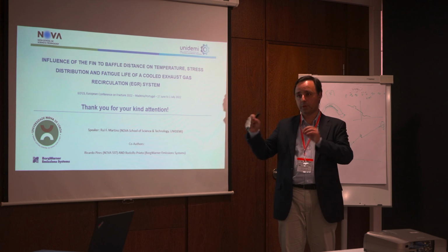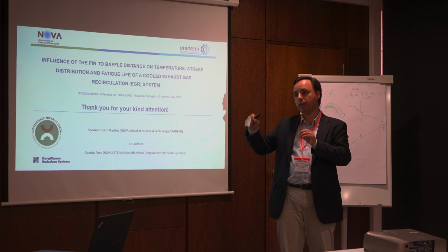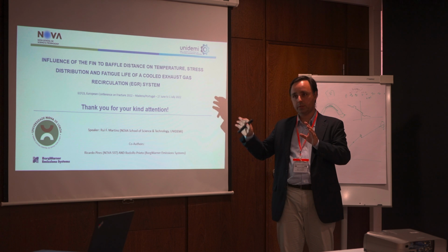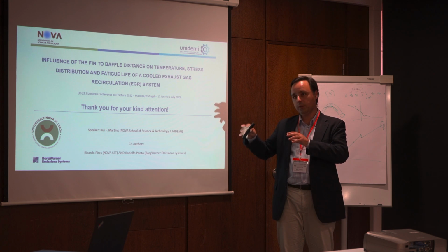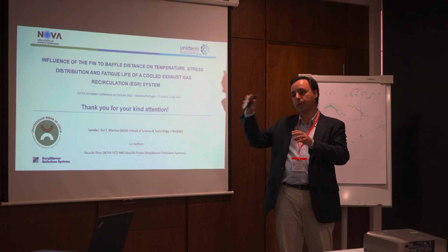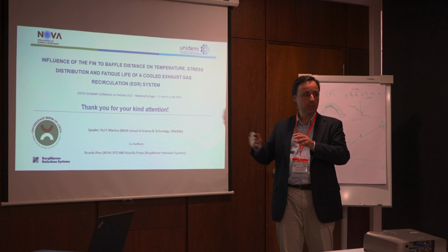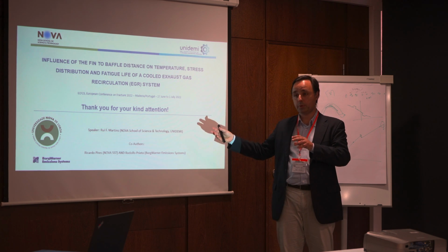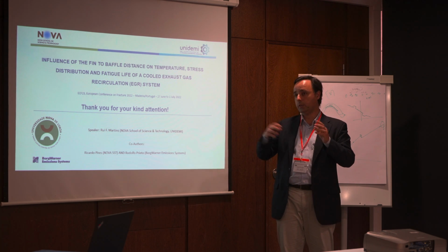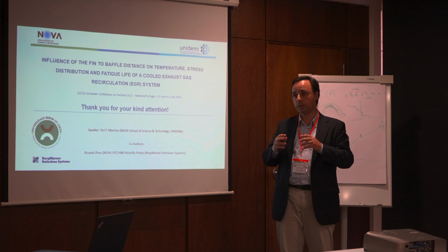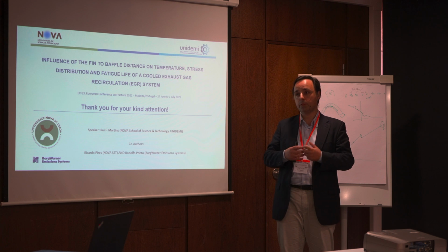So typically the stresses are in the order of 10 to 12 megapascal, more or less, which is much lower than the 300 or 400 megapascal that are induced with the thermal stresses. They are not in the same order of magnitude. So typically what defines the fatigue life of this component is the temperature. The temperature for sure.